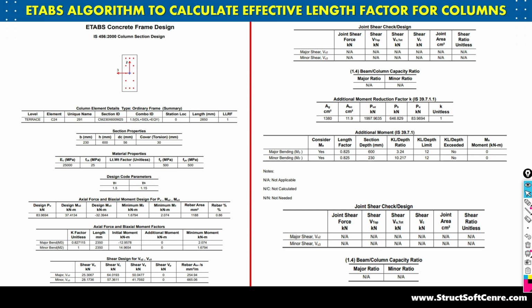Either it is going to fail in the earthquake loading combination, the wind loading combination, or the gravitational loading combination. You are not going to know the problem. Or everything is okay but the orientation is wrong, the modeling is wrong, the analysis is wrong. So you are not diagnosing the problem and directly going to the solution. So guys, you have to look at the reports of the calculation done by or given by your ETABS software. Unless you read the report, you cannot give the solution.